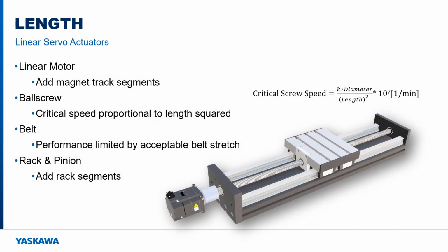Ball screw length is limited once again by the critical speed of the screw. Longer screws begin to oscillate at a lower RPM and negatively impact tuning by lowering resonant frequencies. We'll discuss this more later. A larger screw diameter helps achieve usable speeds, but this means large motors are required to drive the longer screws, even with a small load, unless the speed is very slow.